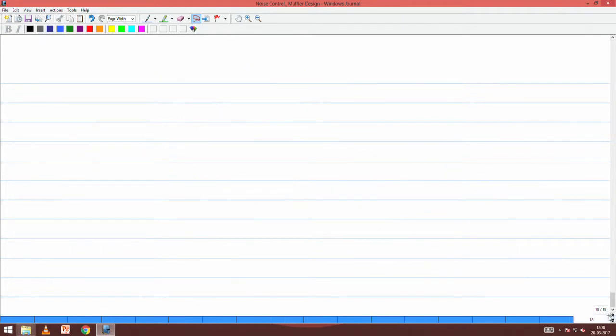So, for the spring element, this is the situation. First, let us understand, is there any quantity which will remain constant between the two ends of the spring element? Is it expected that V2 and V1 has got to be necessarily the same? No, the two ends can have different displacements and hence different velocities. So, in general V2 is not equal to V1.